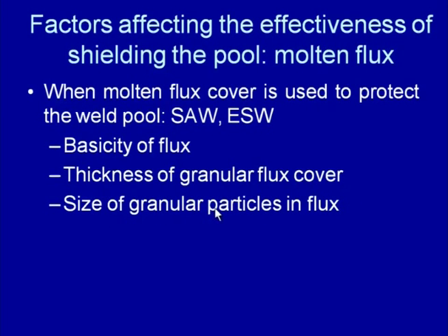The size of the granular particles being used in the flux also affects the effectiveness of this method. The finer particles will decompose and melt easily and will form effective shielding, but these will also decompose at a faster rate, while the coarse granular particles will not decompose earlier, but they will take longer to come to the molten state.